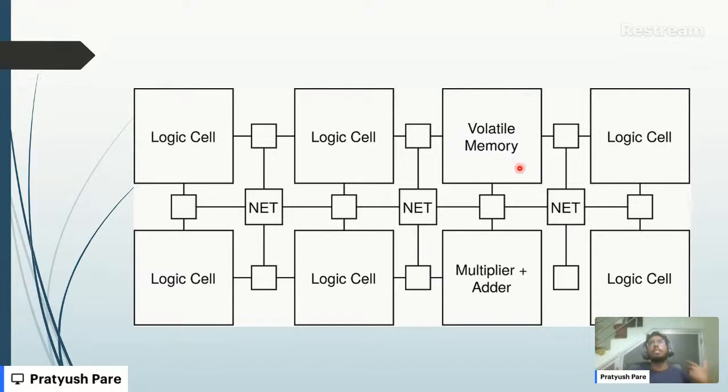And if you have instantiated some adders, multipliers, some floating point adders, some fixed point multipliers, something else like that, very complex, then if the FPGA supports some hard macros of this kind, they will be instantiated in these kinds of blocks, and all the rest of the logic you have written will be constructed inside the logic cells, and the switches will be programmed in such a manner that each block can communicate to each other, as required.